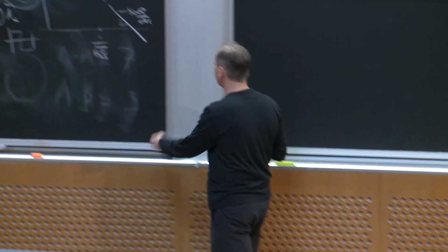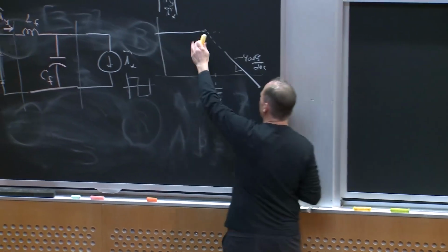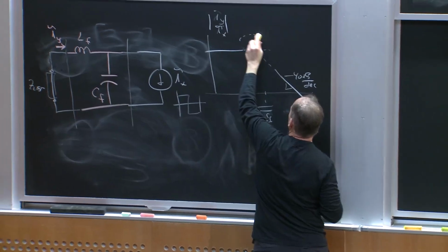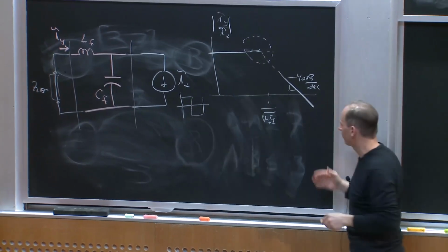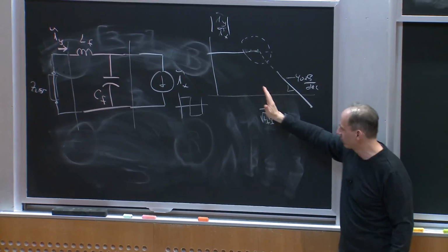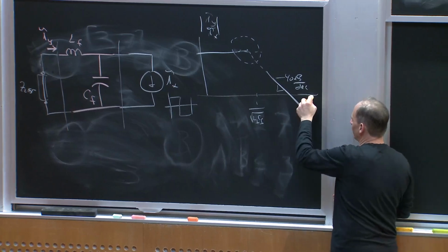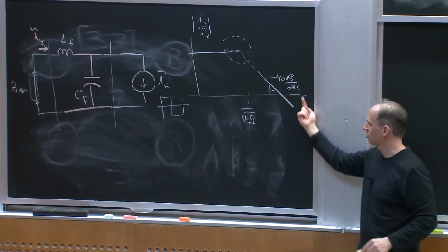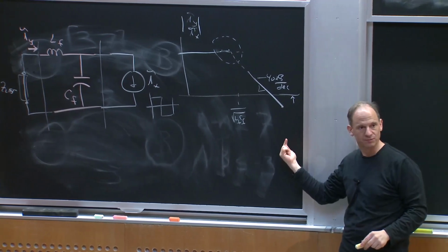And that's great, and I'm intentionally ignoring what happens in the vicinity of cutoff, because keep in mind, the cutoff is some low frequency, and we're going to put our PWM frequency and ripple frequency way out here somewhere, so we're getting lots of attenuation. Okay?